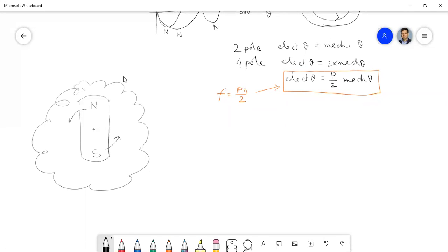But the problem will be there. Your brass commutator will not be required for the stator, and it will not be helpful for the stator, because in the stator you will get the alternating voltage. Then by some other arrangement you have to rectify the voltage. Am I clear?